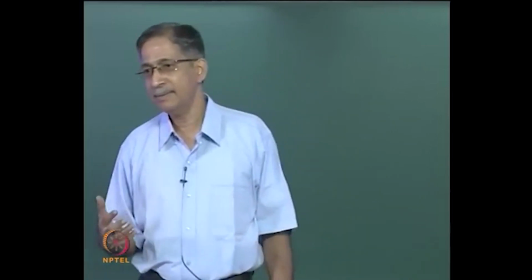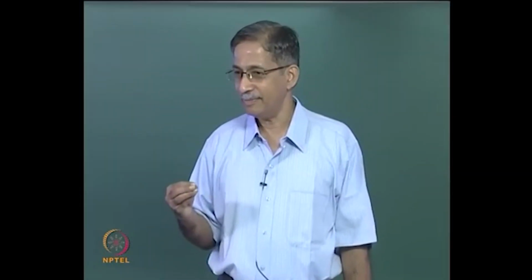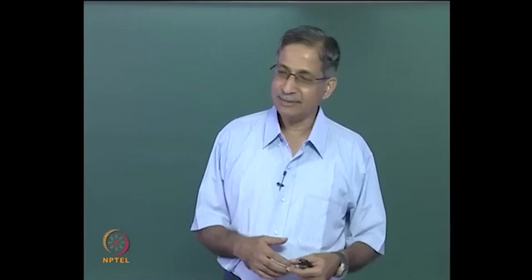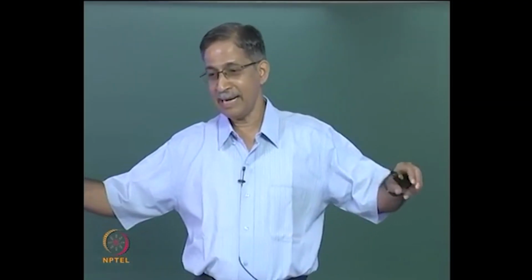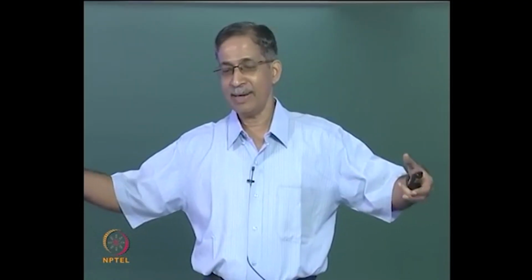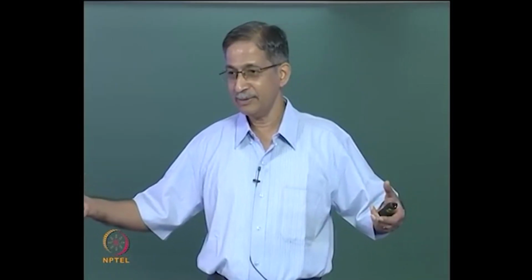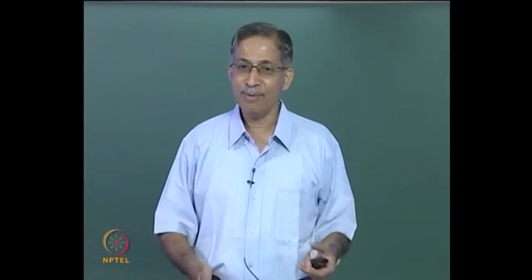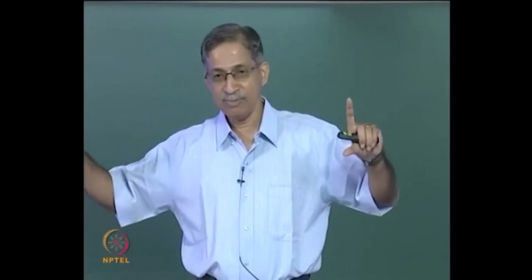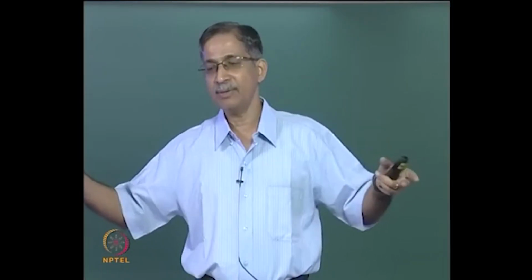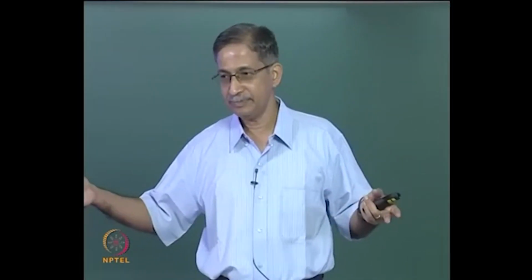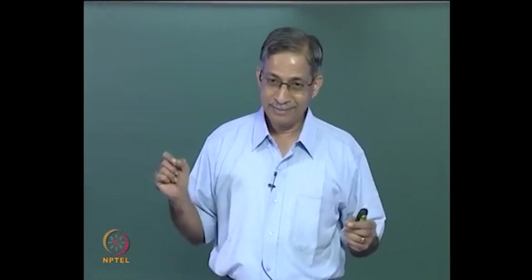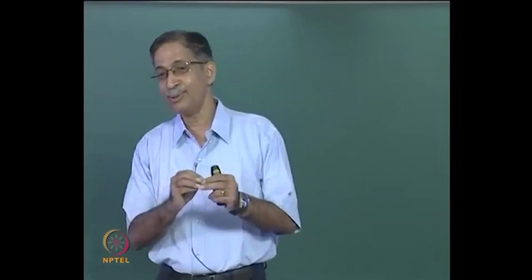So I want you to think, you have to finally bring it to bending moments, right. In the slope deflection method of analysis, we were happy with the end moments being unknown, and we write the end moments in terms of slopes and deflections, and we get the end moments, and then we get the moment in between at any point by interpolating the end moments, right, because your beam is reduced to a simply supported beam. Agreed? So what is the variation of bending moment? That linear, as long as you do not have intermediate loads.